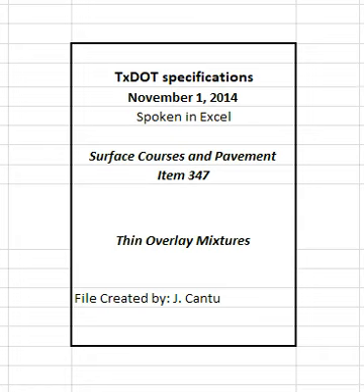4.9 Acceptance Plan. Sample and test the hot mix asphalt on a lot and sublot basis. Suspend production if production test results fail to meet the operational tolerance requirements in Table 8 for any material property for 4 consecutive sublots until test results or other information indicates to the satisfaction of the engineer that the next material produced or placed will meet specification requirements.